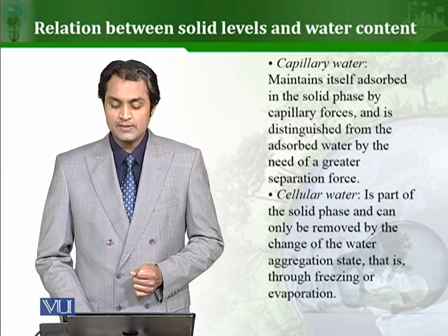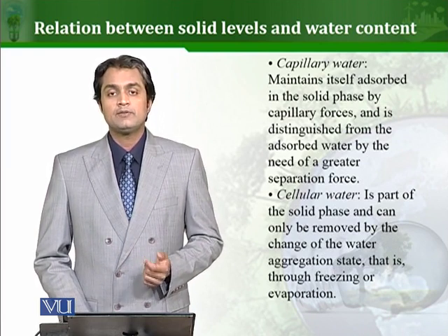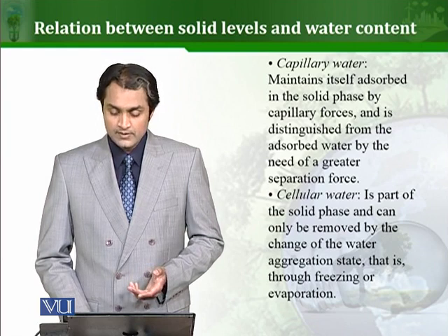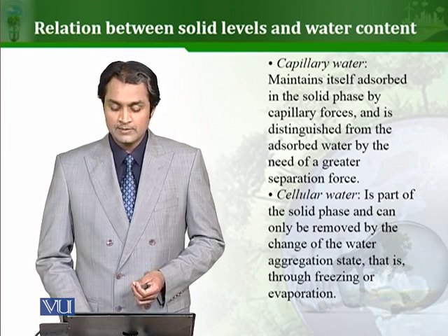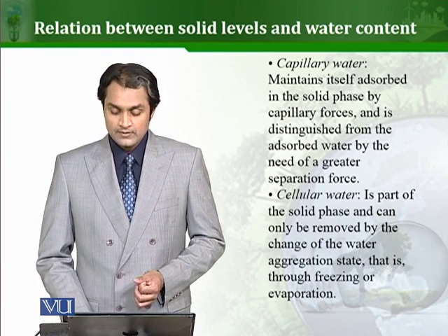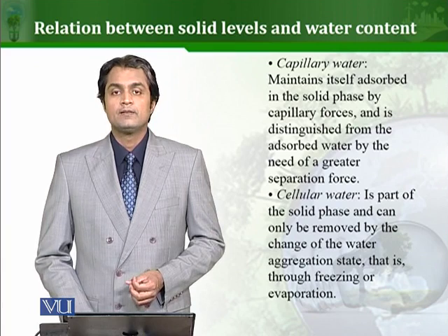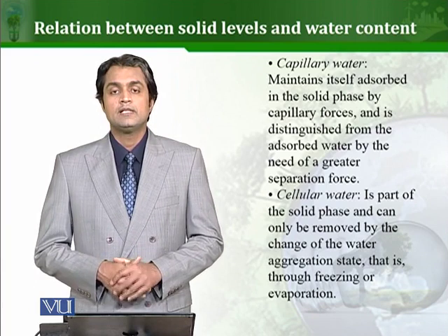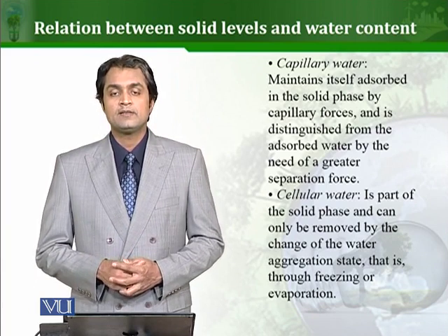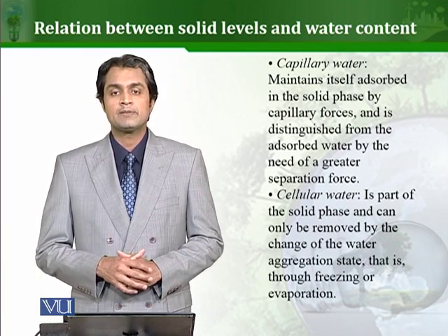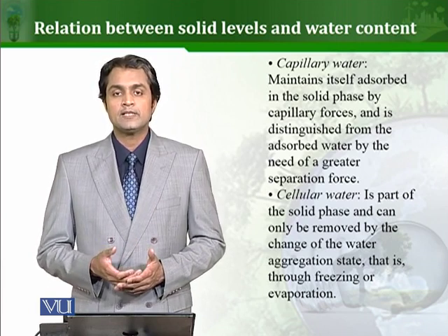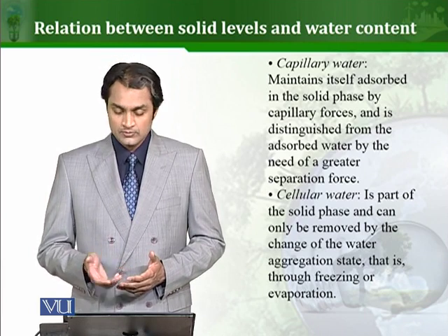And then we have capillary water. Basically it is the water present in the sludge due to capillary force. So it maintains itself absorbed in the solid phase by capillary force and therefore it is distinguished from the adsorbed water by the need of greater separation force. First we talked about free water, then adsorbed water, and then we have this capillary water. Again it is present in sludge and held with the sludge due to capillary action. So obviously more force is required to remove it and different kinds of strategies are needed to remove this water.